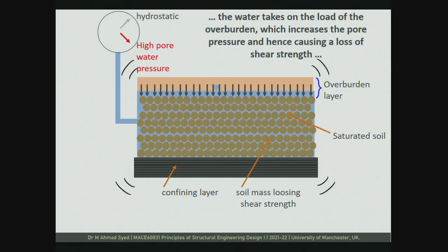contact. Now in addition to that, of course within this short period of time, this high pore water pressure will try to dissipate, and the easiest route with which it can dissipate is that this water starts to come to the surface, right? So when it is starting to come to the surface, you notice that there will be an upward flow of water. So that upward flow of water will exert further force on each grain that we call a seepage force. So the seepage force is because of this upward flow of water, and the upward flow of water is because the excess pore water pressure will try to stabilize, and it can stabilize only by following preferential paths, and the preferential paths are only possible when it tries to come to the ground surface.